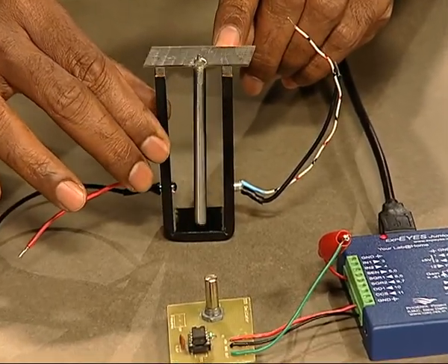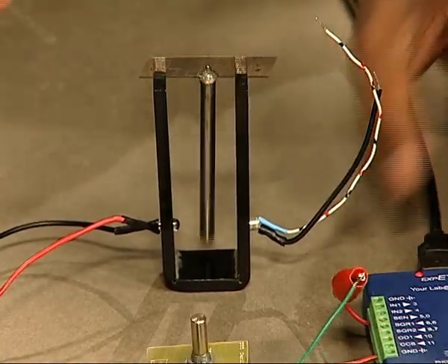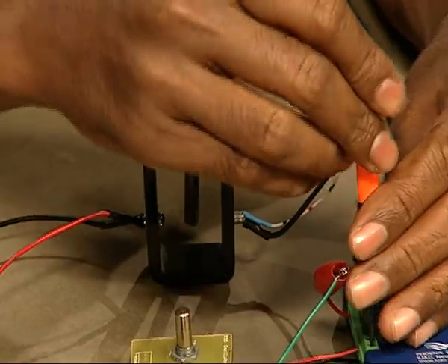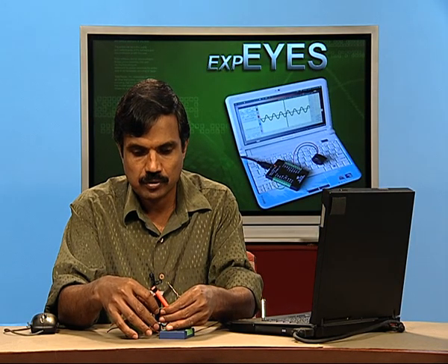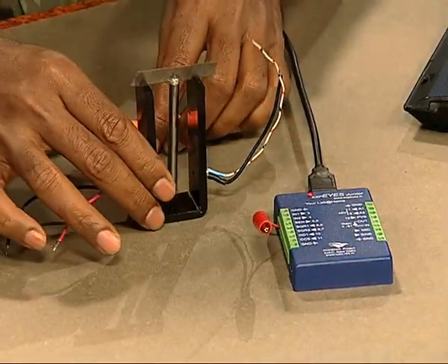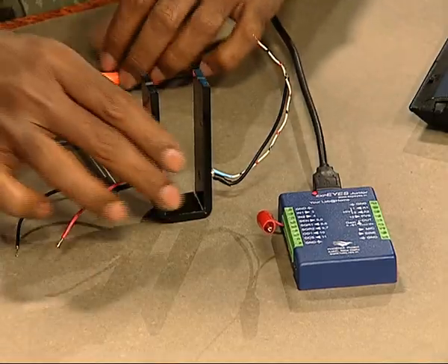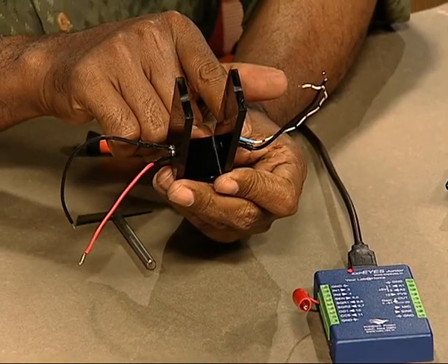So, now the question is, how do we measure this time period? The easiest way is to generate an electrical signal from these oscillations, and how can that be done? What we will do is, we have one LED here on one side and on the other side a phototransistor.